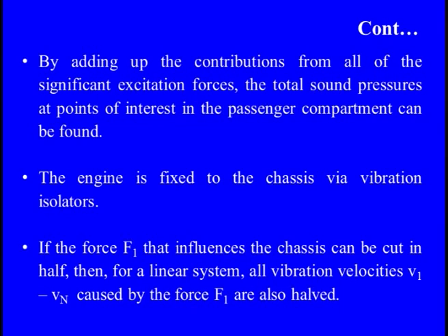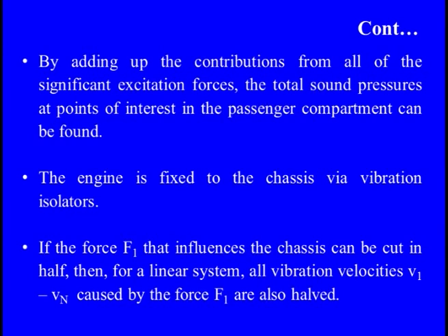So by adding up the various contributions from all the significant excitation forces, the total sound pressure at the point of interest is nothing but that in the passenger's compartment. And we can see what exactly the comfort levels are due to the excitation of various forces, which are turned into vibration velocity and then into sound pressure. The engine is also fixed, and through the chassis, which is basically the medium of transmission, we can apply vibration isolators as well.